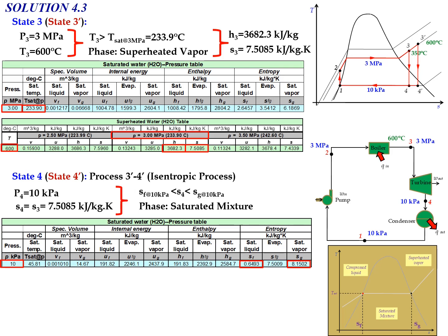So we need to use the entropy and enthalpy equations. First, we need to determine the quality of steam at state number 4. Substitute the values of S4, SF, SFG. So we obtain X4 equal to 0.9144 or 91.44%. So the value of X4 increased compared to the value of X4 in question A. So the quality of the steam improved by using the superheating method.